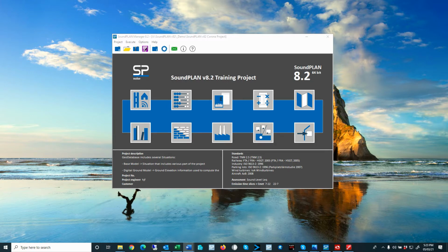Then extreme directivities could be from loudspeakers, a bass loudspeaker, tweeter, so that could be something to model in SoundPLAN. Then we have firearms, rifles, guns, cannons, or human voice. If you have a source that represents a person, there's of course a lot of directionality with screaming or someone talking, where the body by itself offers certain shielding and also radiation patterns. So these are all different examples of where it's interesting to define a more detailed directivity of the source.